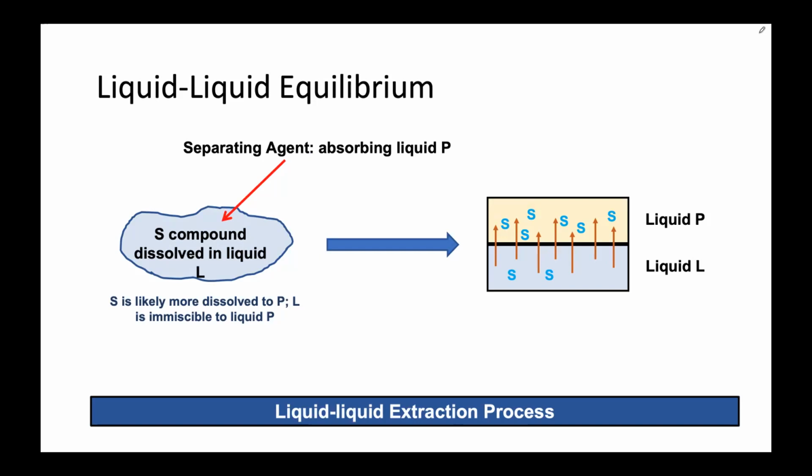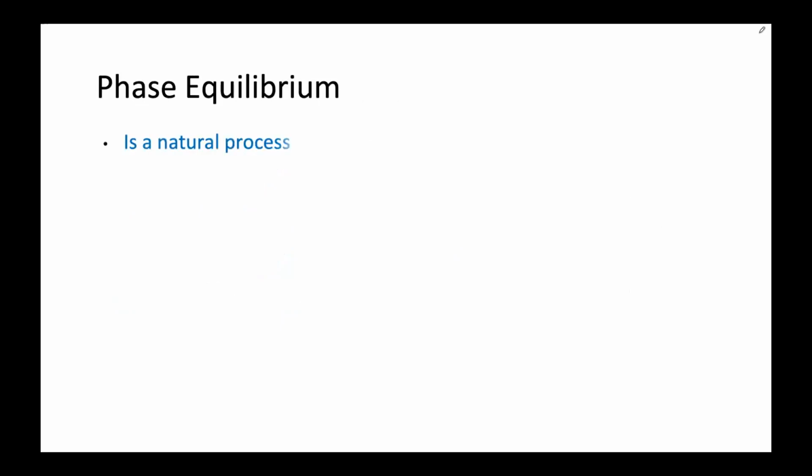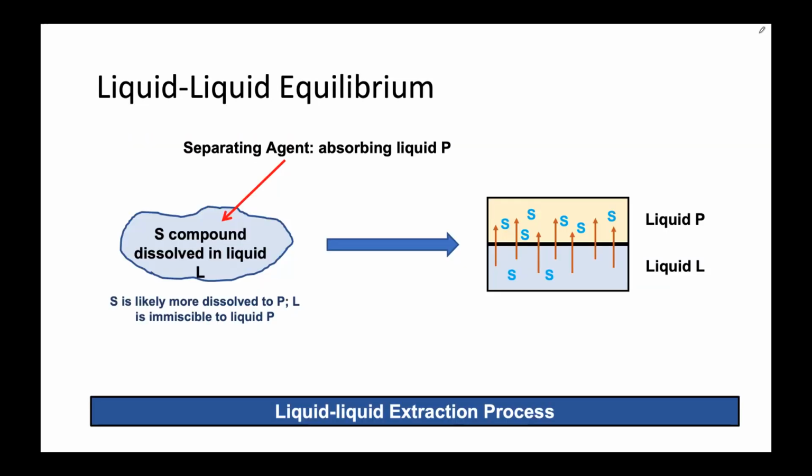But sometimes distillation is not preferred, because in distillation we use heat. Yeah, we use energy. We heat up the solution. Sometimes a solution can't be heated, for example essential oil. If you heat it too much, then maybe some of the organic compounds are going to be broken, and then it's also not going to be good for the substance.